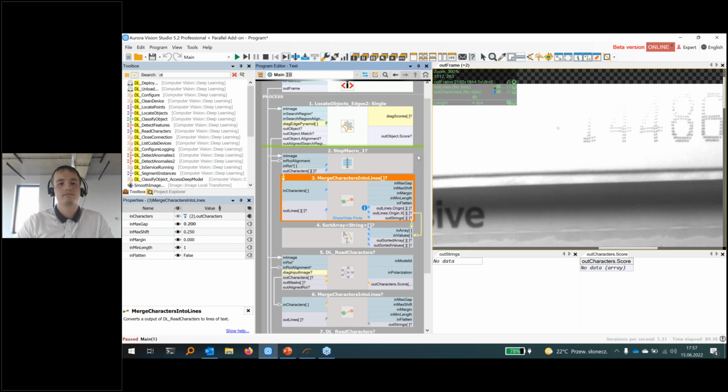Thank you very much. Can we detect bad printing? For example, can we detect blurred characters printed on a label and alert the user to reprint that bad label? This is not really in the scope of this tool, because what you're talking about here is OCV, optical character verification. And for that, we need to make sure what the font already is, so that we can compare it with the pattern, basically. And this tool, since it is trained on so many fonts, cannot really judge how accurate the character is. Of course, save for the score value, which might not really give you the information you are seeking.